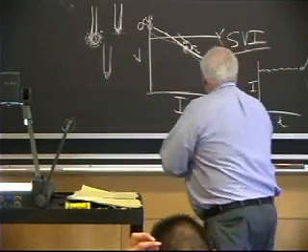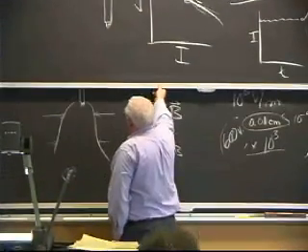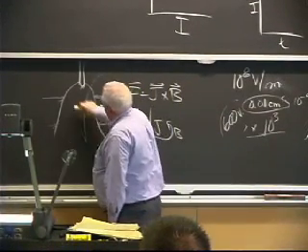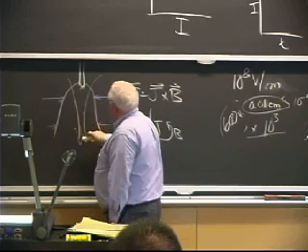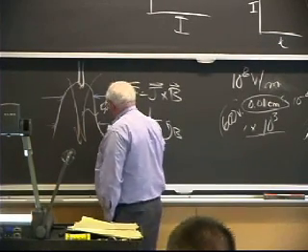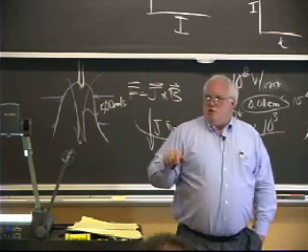Okay, let's go back to plasma jets and what we do with arc pressure. We talked about the fact that the plasma jet drives flow in here, and I think I said 500 miles an hour. It's actually 500 meters per second, which is faster than 500 miles an hour. This would be supersonic flow if it were not a rarefied gas.